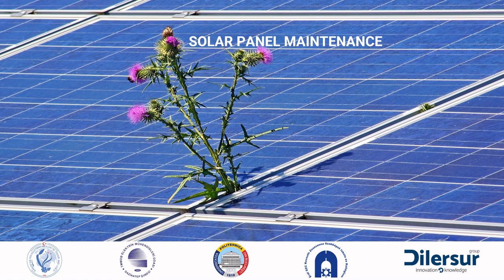The general activities that must be conducted during visual inspection of a solar plant are as follows. Equipment grounding verification. Identification of hazards. Inspection of weatherproofing systems. Inspection for wiring damage.